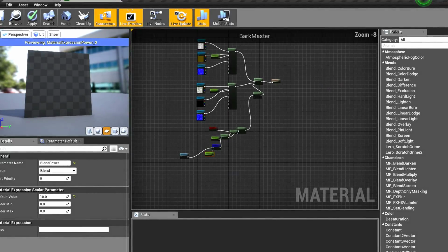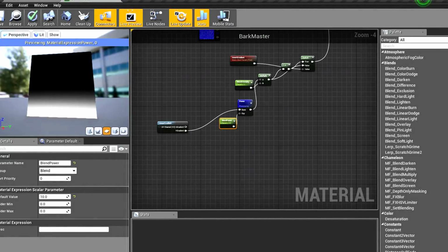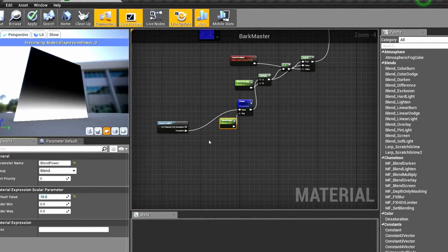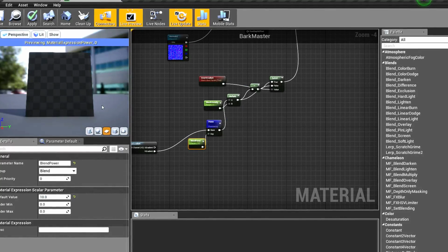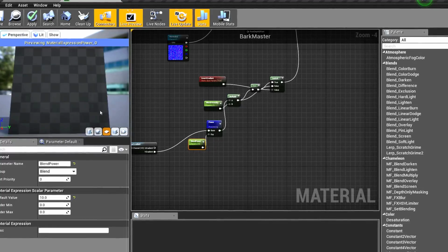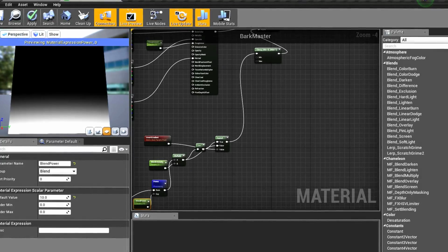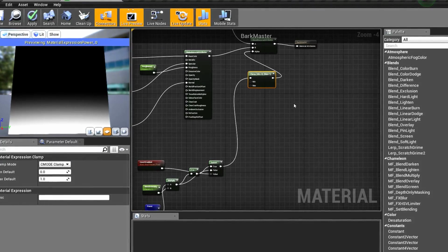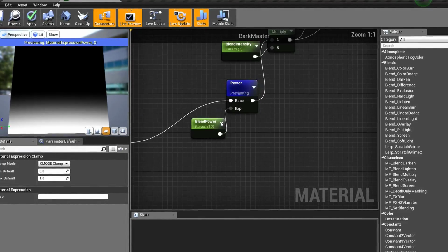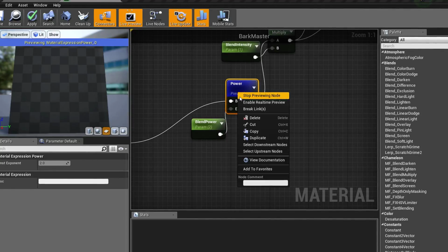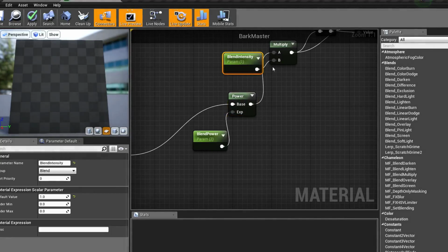Let it load. Now, as you can see, we have changed the blend direction. Now you will soon get a very bright or dark color that is not in the range of 0 to 1. So in the end I am using a clamp node to bring it into those values. Alright, now I'd like to set this back to 2. That's a very good value in this case.